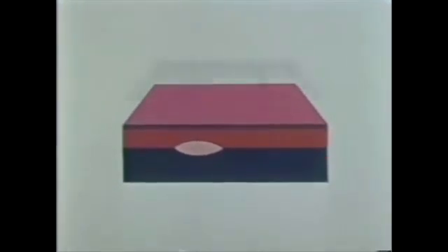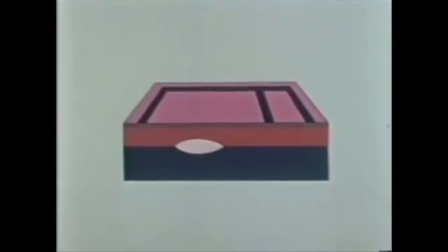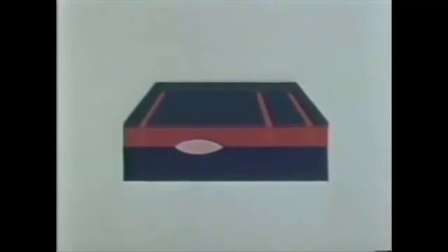Now we're going to strip off the passivating layer and grow a new layer of silicon right on top of the diffused wafer by a process called epitaxial growth. Now we form electrically isolated regions on the wafer by a process of diffusion, photosensitive coating, masking, exposure, rinsing, etching, and diffusion. Next, we prepare the individual parts of the integrated circuit. First, a transistor base and a resistor. The same procedure is followed.